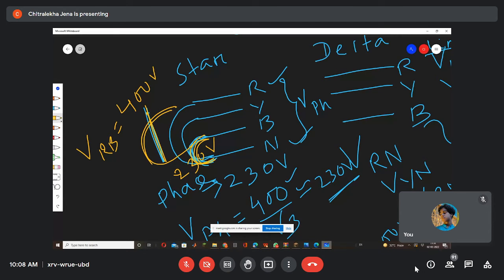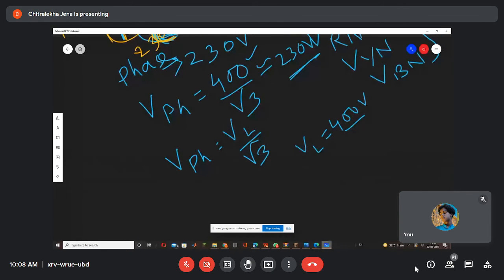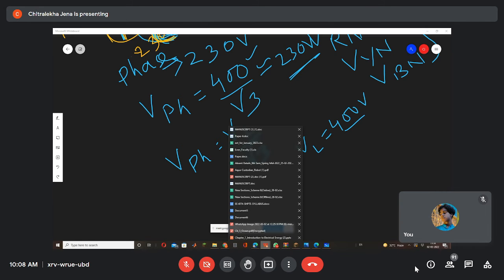We do not talk about the phase voltage now, because we will read later that phase voltage equals line voltage divided by √3. So when the line voltage is 400 volt, the phase voltage is 230 volt. Am I clear now?